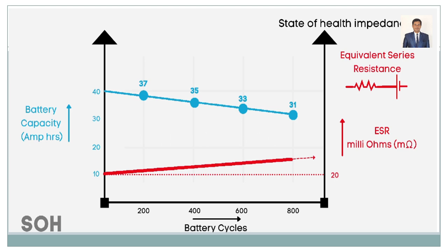Right? This is just because of the rise in the temperature. Sometimes when you charge the battery, there is a rise in the temperature. Sometimes there are bad cells in the battery module, right? So during the driving conditions, during discharging also, the temperature will rise, and the internal resistance also makes a lot of impact on the state of health. All right. So this is the one example we have taken to make you understand that very clearly.